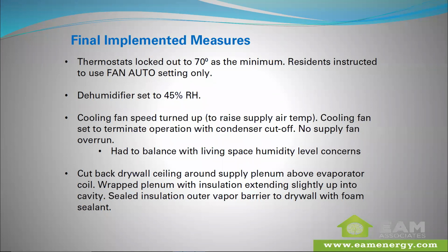So in this case, when they started having problems in the summer of 2018, they installed these wall-mounted dehumidifiers in that laundry closet because there was a convenient drain that could be used for the condensate. And they did a good job in that localized area, but because they're just pulling air and exhausting into the same space, they're not creating any kind of a flow gradient across the whole house. So they can be relatively ineffective, especially in larger spaces.